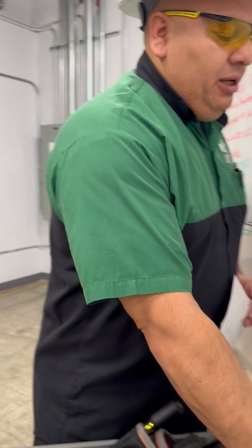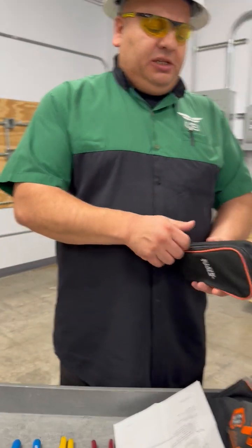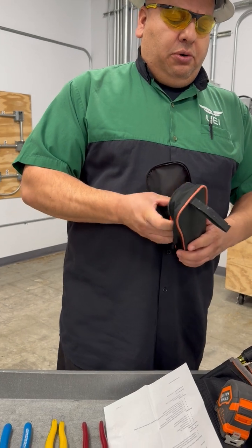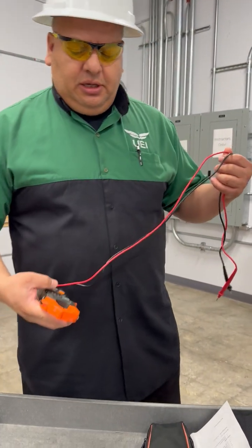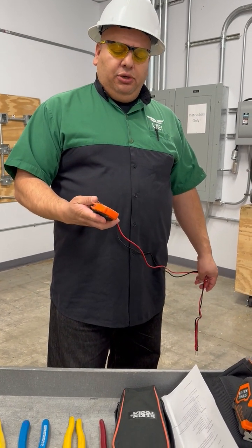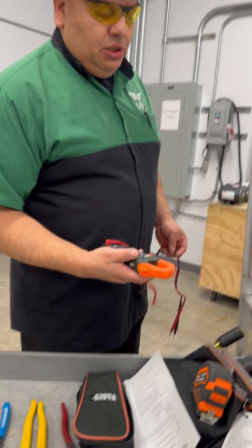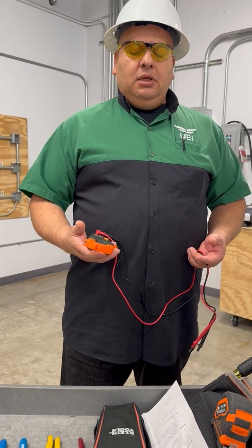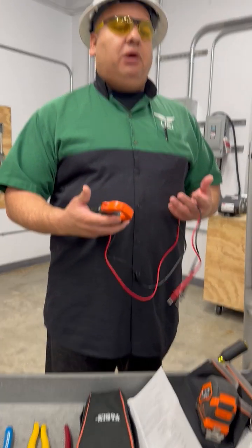We have a multimeter. One of the things I like to do is use the multimeter as much as I can on every project, but let me illustrate it here first, real quick, because this is usually where I do it and give it to everybody as generalized instruction. How can I use the multimeter before I apply power to my circuit to verify that it's going to work, to verify that there's not going to be a short circuit, to verify that there's not going to be a ground fault?